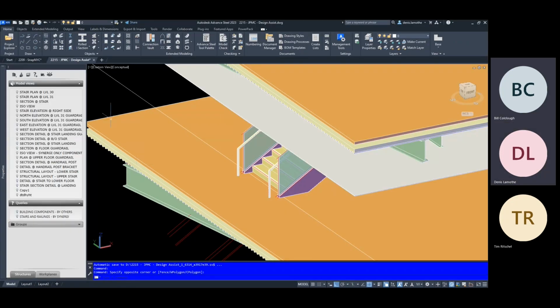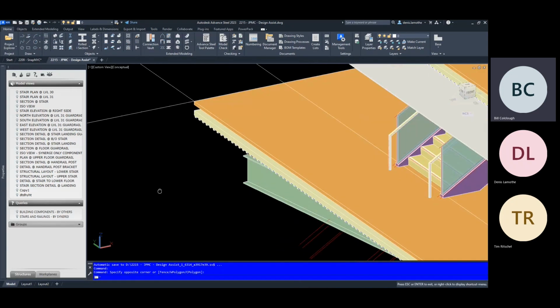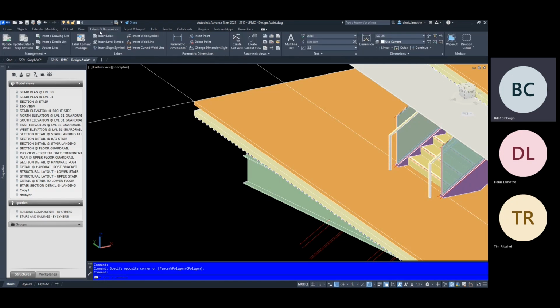That's a feature of SolidWorks that I used to use a bit when I had dimensioning issues or dimensions that wanted to be driven off of a fixed dimension. Right. And so I could incorporate that into a formula and always drive the dimension. If one changed, everything else changed accordingly.